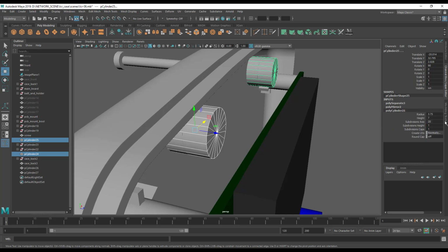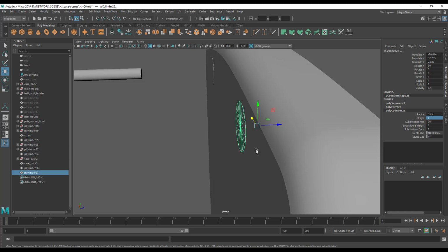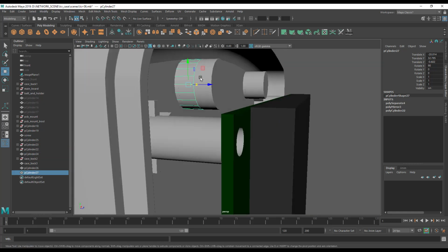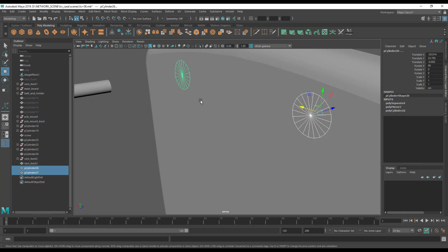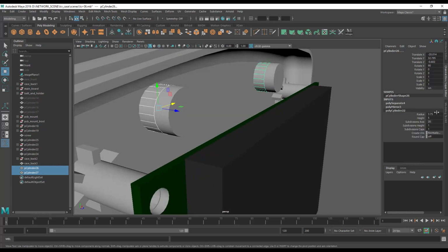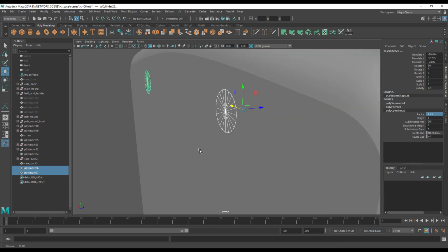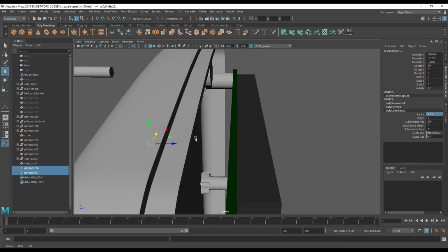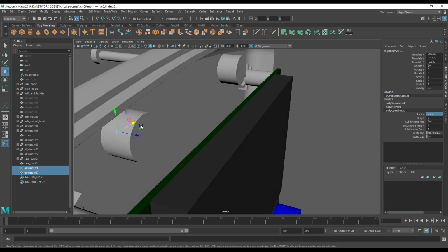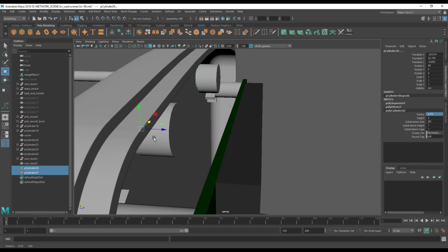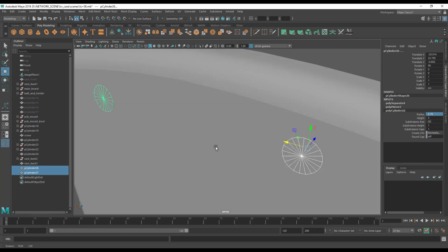Warning, math, although very simple math. Still, my tired old brain sometimes has trouble with that. Yeah, that'll leave 2mm of plastic on the top. So let's select both of those, make them 5mm radius, so 2.75, and use them to punch holes in this. That will leave us with a screw that goes 5mm into the case, and also 2mm of plastic on here to give us some extra support when we bore another hole through it.